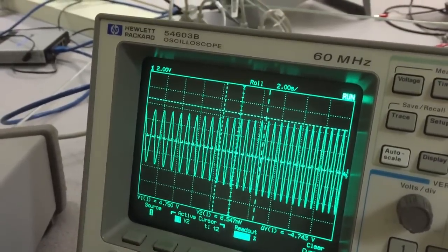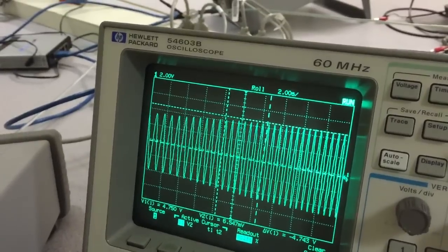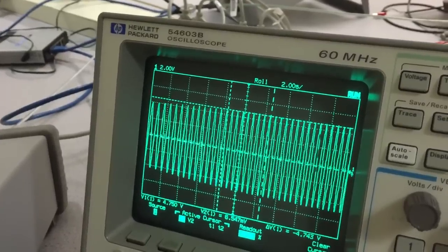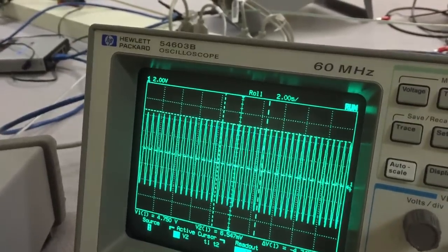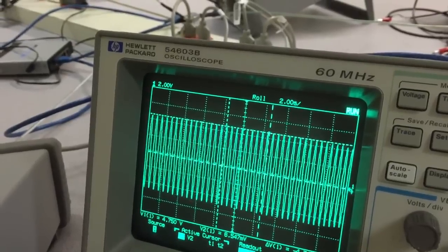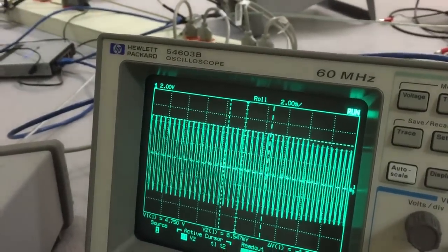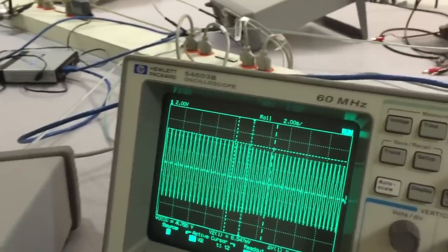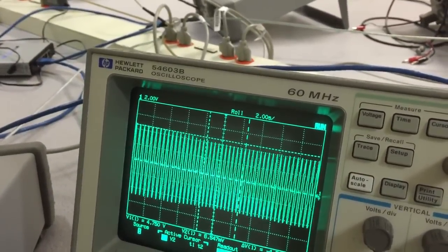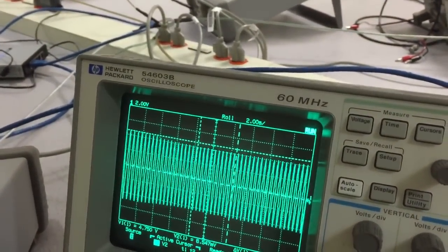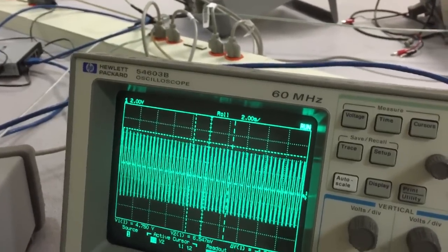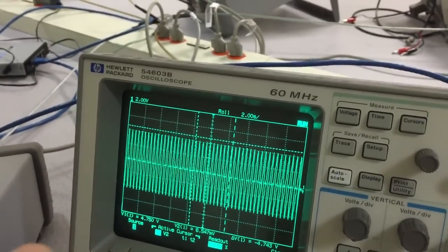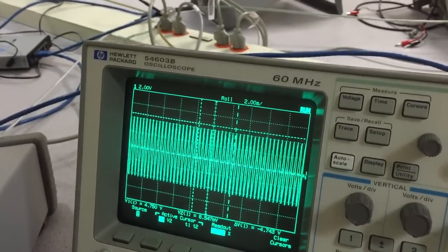Oh, it touches the cursor now. It's about 1.9 hertz and it touches the cursor. It's just above the cursor. Oh, it's going down again. It's now 2.4 hertz. So the peak is smaller than 2.4 hertz and bigger than 1.8 hertz. So it's actually between 1 and 3 hertz. Try to get as exactly as you can to the peak frequency. Once you get the peak frequency, you measure the peak amplitude from here. Using these values, you can find the motor constants as you derived in the theoretical part.